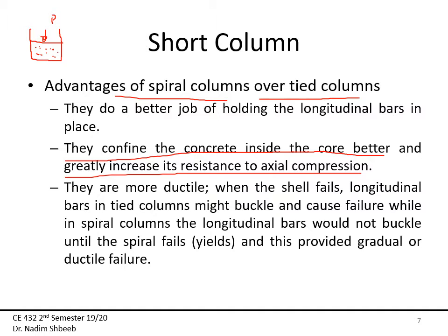Now that load will transfer to the cylinder walls. As long as those cylinder walls hold, you will have no failure, right? And because it's a cylinder, we call these hoop stresses. The spiral has the same, and this is analogous to the spiral column as well. As you start increasing the load, the concrete inside that core, inside that spiral, will transfer its excess force to that spiral.